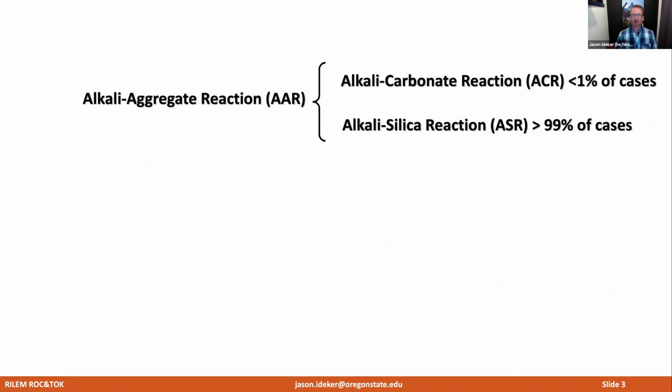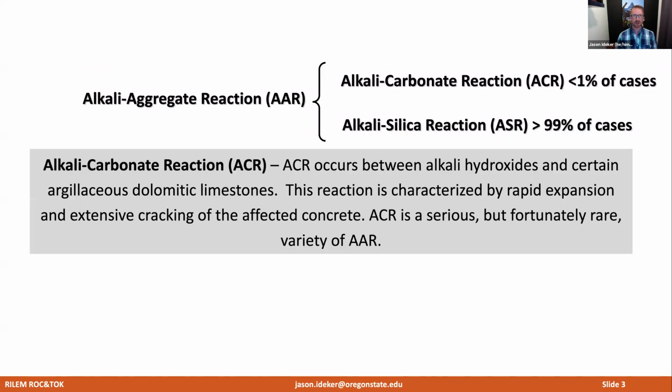So as I mentioned, alkali-silica reaction actually falls under a subclass of a larger reaction called alkali-aggregate reactivity. And ASR is responsible for at least 99% of all cases, if not even more. There's a second type of reaction, though, called alkali-carbonate reaction, which is responsible for less than 1% of all cases of alkali-aggregate reactivity in concrete.